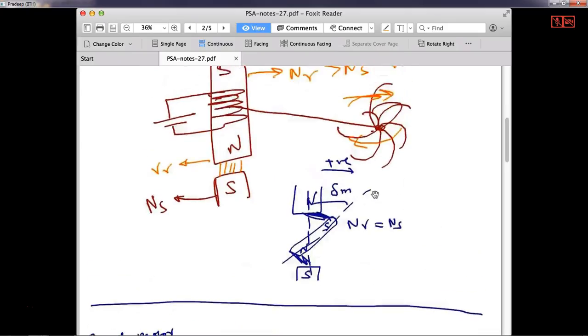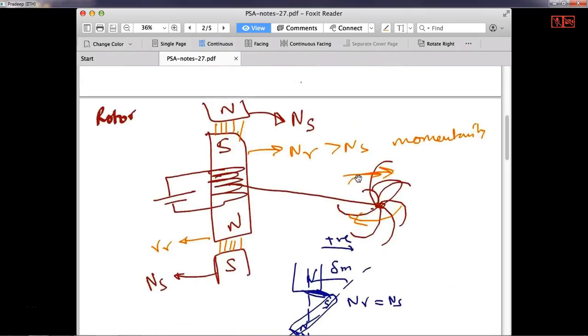So now the issue is, if I gradually add the power, then it will increase gradually and there is scope for this magnetic locking to be maintained. But if I have a sudden increase in the load, the magnetic locking will be lost and therefore the motor will come out of stability. So that is the stability problem.